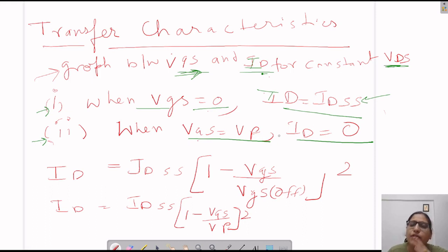when VGS is very high, let's suppose -4 or -5 volt, then what is happening? The depletion region width is increasing abruptly. If the width is increasing that much, a very narrow channel or no channel is left. In the ideal condition, we see that these two are touching each other. We know that they will not touch because of the electrostatic repulsion force, but we assume that so that we can find the ID value. Something we have to assume for finding the most appropriate value of